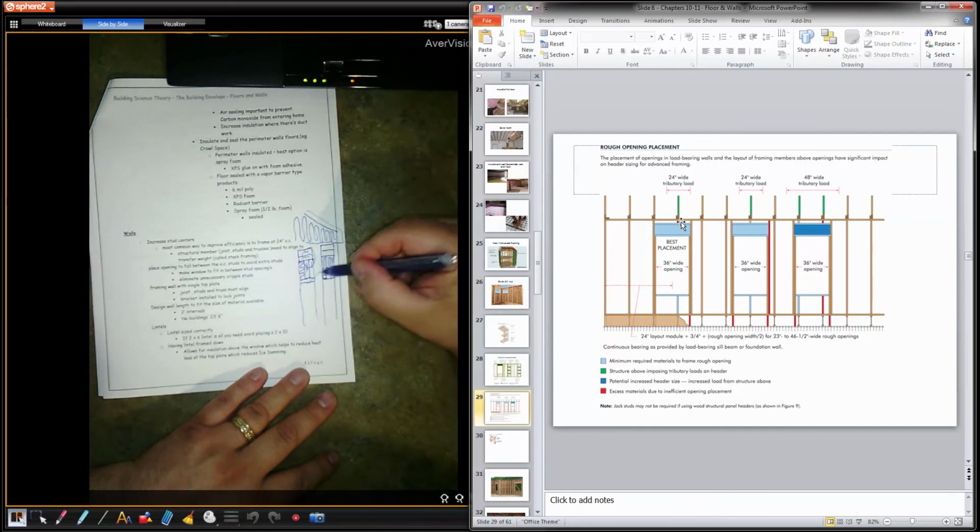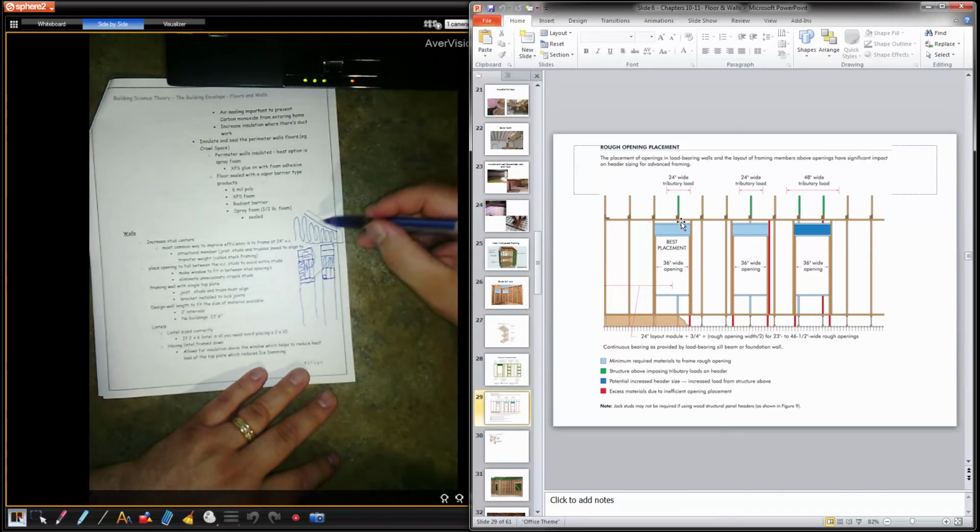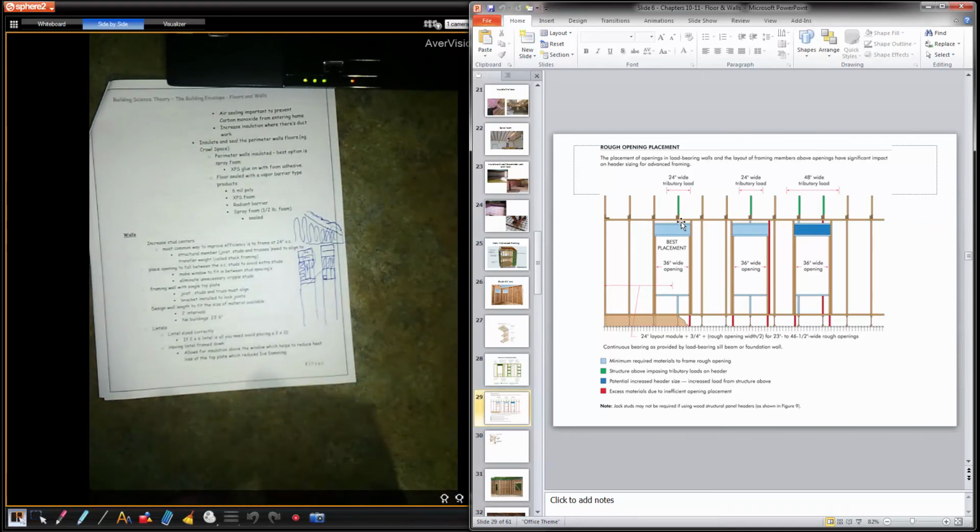Whereas if we have this going on, maybe just a single plate down, because we're doing advanced framing, there's less thermal bridging, therefore less heat loss entering into that vulnerable area, an easy path going through the insulation that's compressed, right? And then that creates ice damming. So we get hot air coming through, melts the snow, and then it freezes. And then the next day, same thing, melts the snow, and all of a sudden we have water here. Now that water starts traveling up the shingles, going underneath and then getting into the structure.